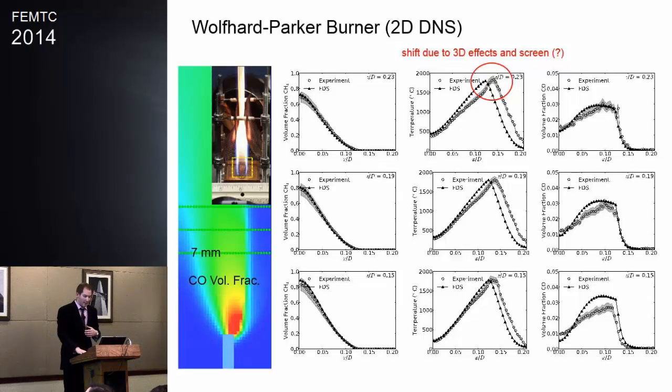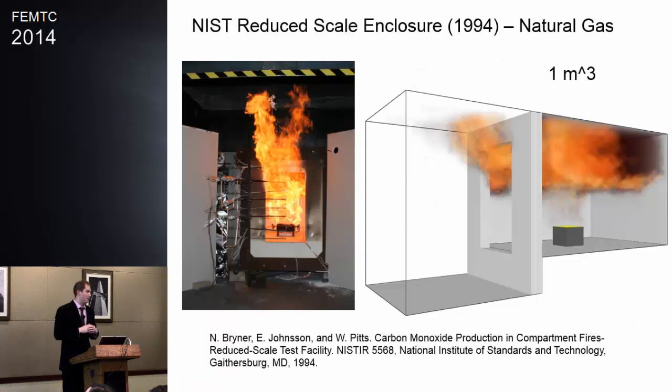Anytime we do a simulation, if we're going to say this is the mechanism we're using, we want to look at different scales. The first scale, like I said, was about a 10 millimeter domain with 0.5 millimeter to 1/4 millimeter resolution. And we did it in 2D and in DNS as opposed to our typical LES simulations. And so here we went to a next larger scale. These were experiments performed in 1994 by Nelson Briner and company.